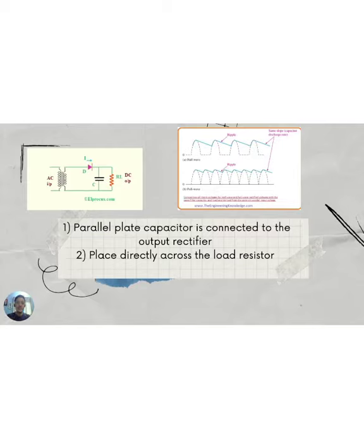The capacitor filter can be designed to pass low frequency signals and high frequency signals, or even a certain band of signals can also be filtered with this type of capacitor. The output frequency of a half-wave rectifier is 2 times smaller than the output frequency of a full-wave rectifier. Therefore, the full-wave rectifier is easier to filter due to the short time between the peaks.